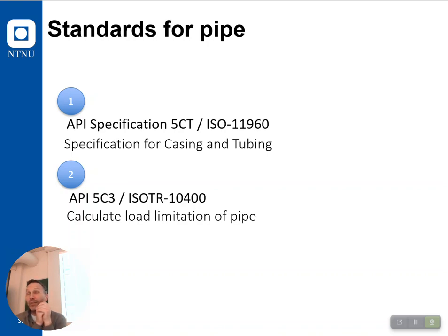They actually scanned the full joint, and that was saving us a fortune. That was a campaign of many wells where we reused the tubing. And once you know that it's less than 12.5% wall loss, all your calculations are valid.